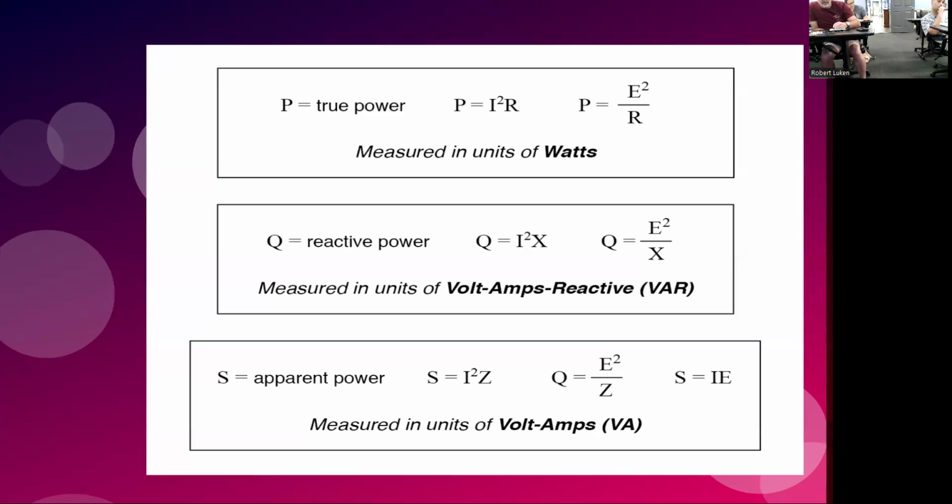And we simulated that without any loads on it, just an open power transmission line. And it was 2 megavars. Just because of the capacitance or inductance, I forgot which way it was. But it was only about 4 amps at 500,000 volts.